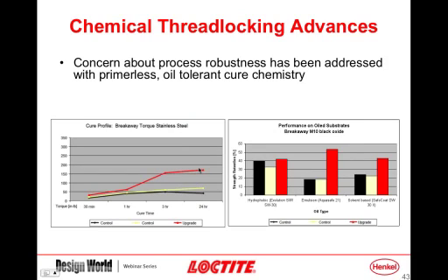This would be the newer, where even on a stainless steel surface, which does not have any free metallic ions, the activator system within the adhesive is able to cure, and cure relatively quickly, without any secondary operation. The main benefit of this is that in a production environment, you have a more robust system that can tolerate different surfaces without having to have a secondary operation.